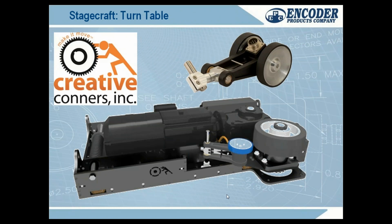Another safety application here, this is out of Stagecraft. We've got a gearbox. This is a 90-degree gearbox here that has an encoder of its own in it, and it's running this big caster wheel here. So this big caster wheel runs up against a 40-foot diameter turntable on a Broadway stage. Well, there's human beings, there's actors and actresses on that table. What if that table jammed? What if a costume got stuck and jammed it and somebody's getting pulled into the table?